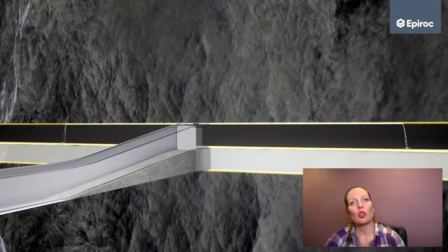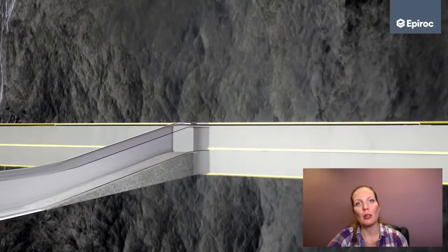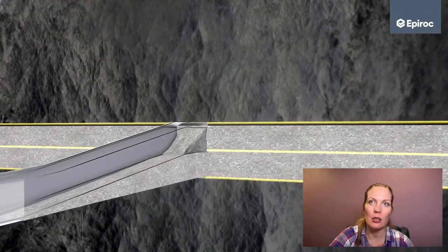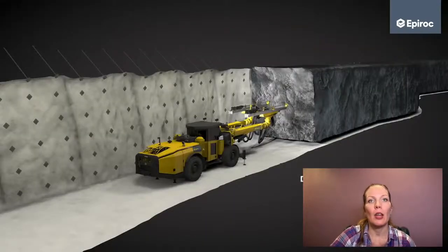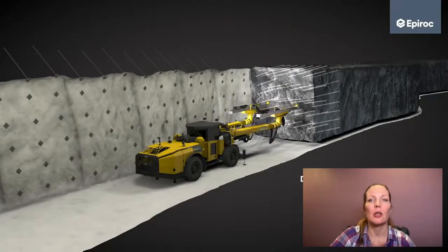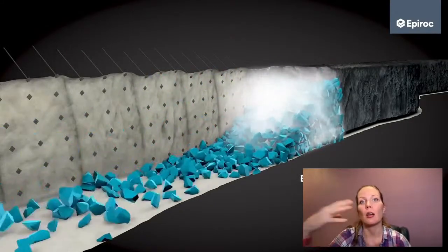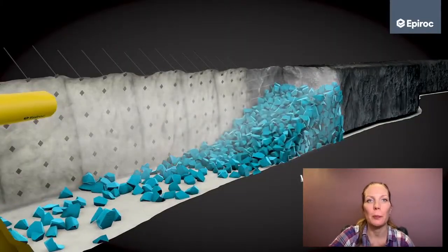A neighboring stope in the same ventilation wing cannot be opened at the same time, and drilling the next slice cannot begin until the backfill in the slice below has fully cured. On the resource side, it's helpful to maintain loading charts for drill rigs and backfill plans so that peaks in cement and/or aggregate demand don't overlap across multiple stopes.